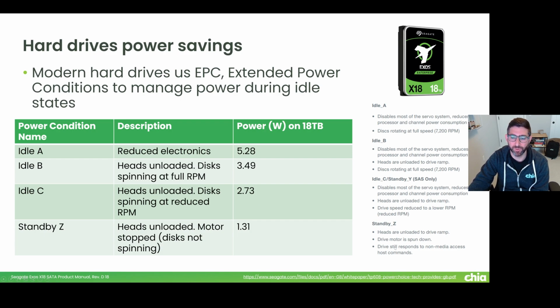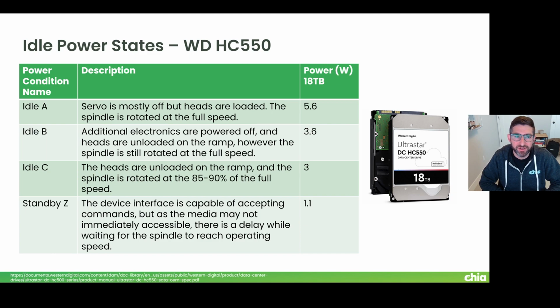And standby Z is where the motor's spun down, heads are unloaded, and the drive still responds to non-media access commands. So when it gets a command, it can spin back up, and that spin up time takes about 10 seconds. I've taken similar specifications from the Western Digital HC550 specification. You can see it works exactly the same way.